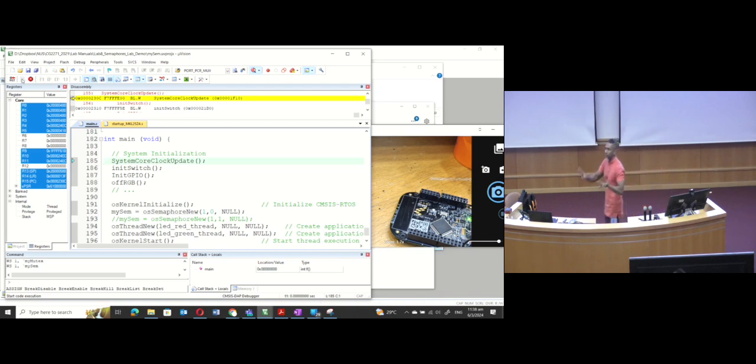So I can say the task blocks, waiting for a semaphore. Then when task A finishes something, I release a semaphore, and task B continues. And when task B finishes something, task A continues, or task C continues. So a semaphore provides you with one option of synchronizing the behavior of multiple tasks. Again, it is just one option. We will explore a lot of other options, such as events, flags, message queues, and so on next week. So for now, let's just understand this first.